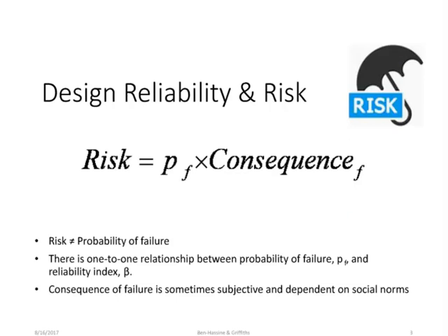The first thing I want to talk about is the concept of risk, and risk is not really a probability of failure. It is not how likely something is going to collapse. It is a combination of that likelihood and also the consequence of that event. So it's important to remember that risk always has a cost or a consequence component.